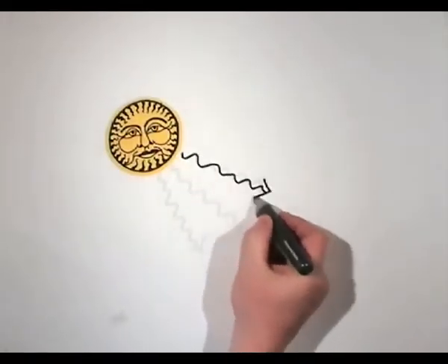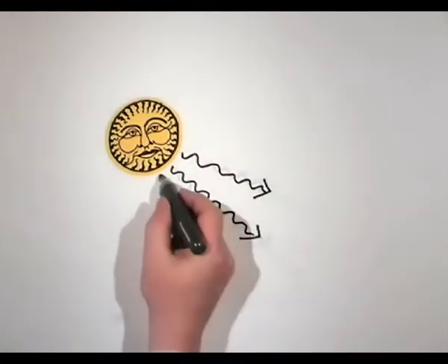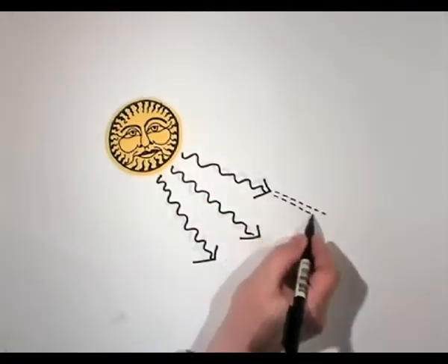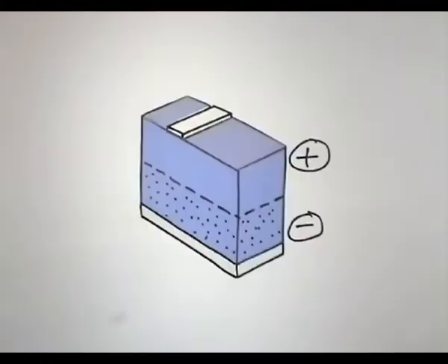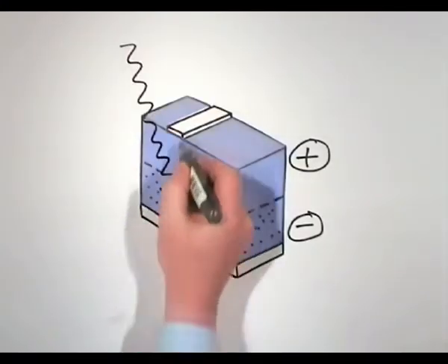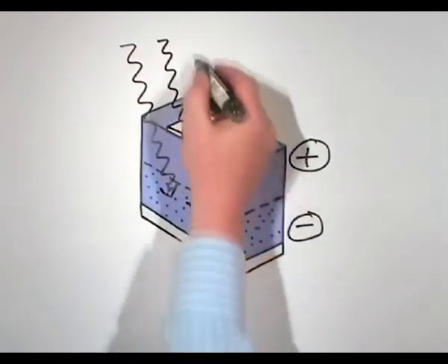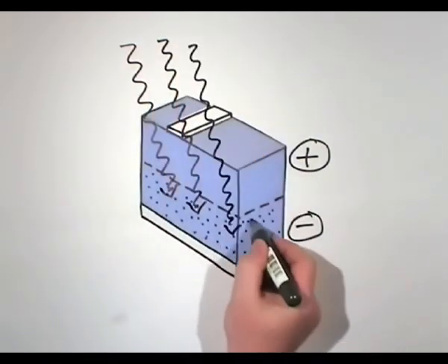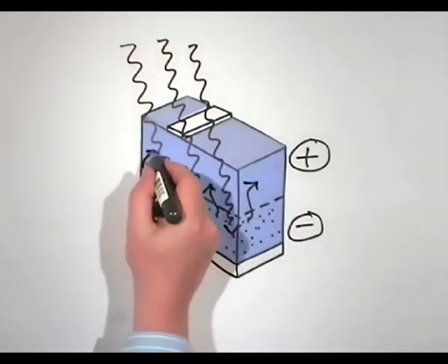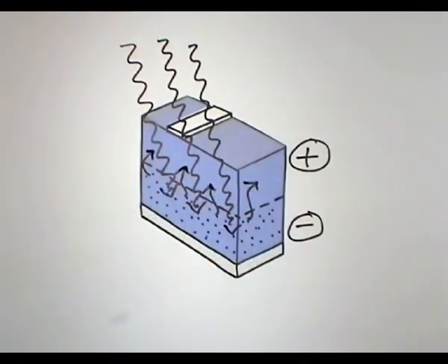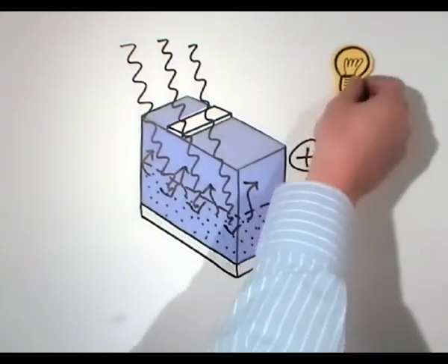Sunlight is made up of streams of particles called photons, which are units of electromagnetic radiation, in other words, a form of energy. When the photons penetrate the silicon wafer, they give loose electrons they encounter extra energy, enough to enable the electrons to move across the electrical field. Electrons begin to flow through the wafer and round the circuit. The direction they move in depends on how the circuit has been set up. So now we have a flow of electrons, in other words, electricity.